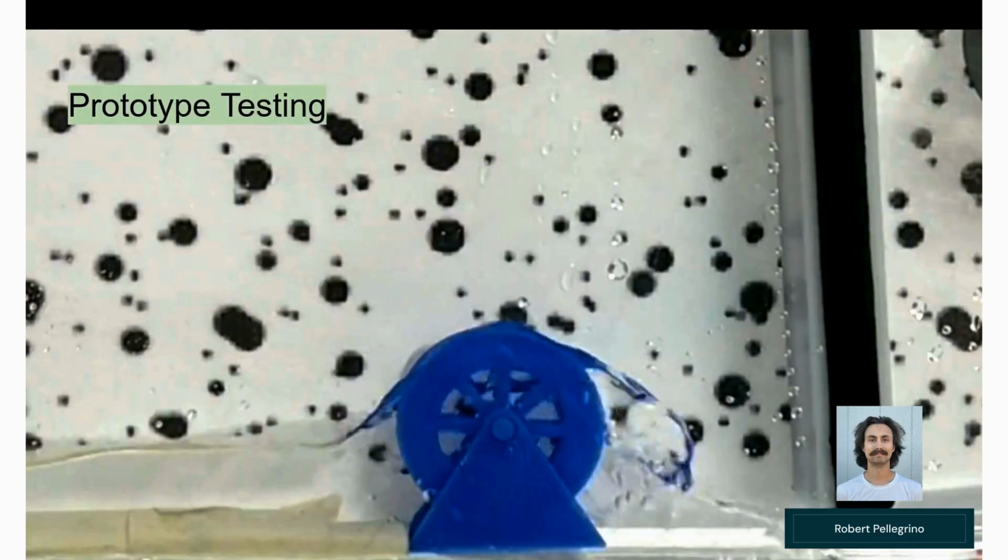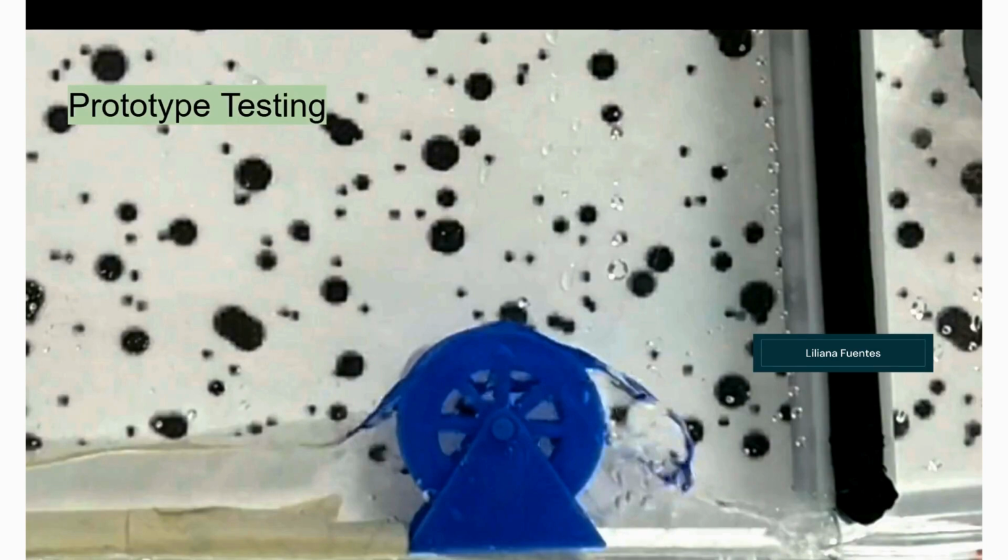Instead, we decided to place a small hose in the tank held by the blocker to increase water velocity and direct the water at the wheel. This setup provided a more focused flow of water and allowed the wheel to spin freely. Once we had a recorded video of water passing through the water wheel, we imported it into PIVlab to analyze the velocity of the water before and after passing through it.